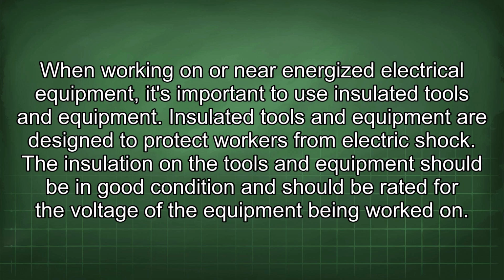When working on or near energized electrical equipment, it's important to use insulated tools and equipment. Insulated tools and equipment are designed to protect workers from electric shock. The insulation on the tools and equipment should be in good condition and should be rated for the voltage of the equipment being worked on.